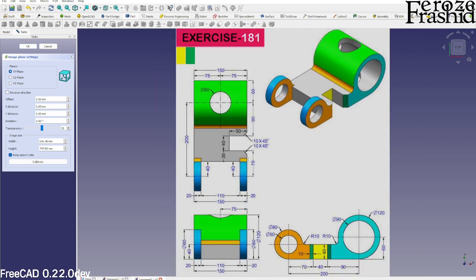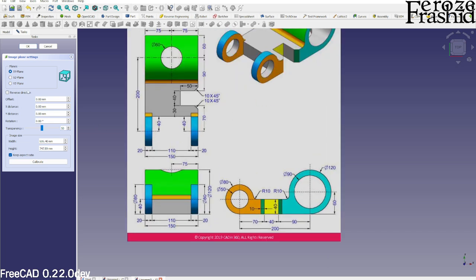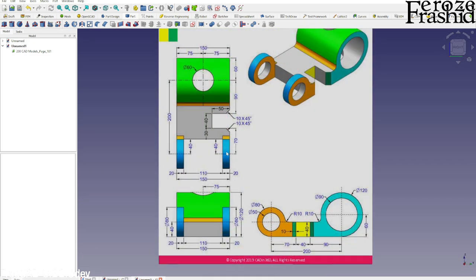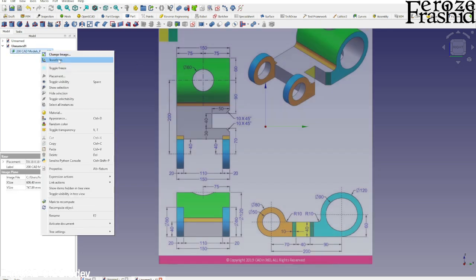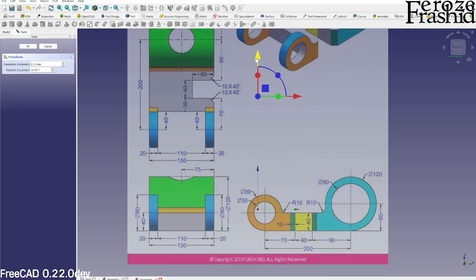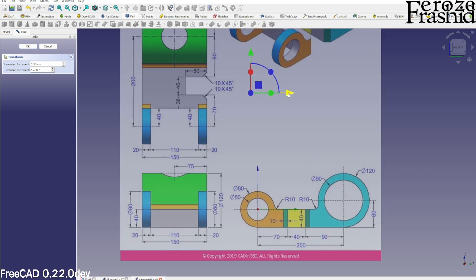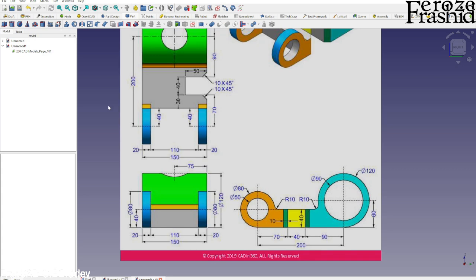All right, I want to start working on the XY plane. No, maybe on this side, the YZ plane. So let's put it on the YZ plane and go there. From here, I want to bring in the Axis Cross by pressing AC on the keyboard and relocate the image. So it has two circles on the cross section. Any one of them will be my pick. I'm gonna go ahead and take this one. So this is my center of workspace, and that's all we need the Axis Cross for. So let's take it away by pressing AC on the keyboard.